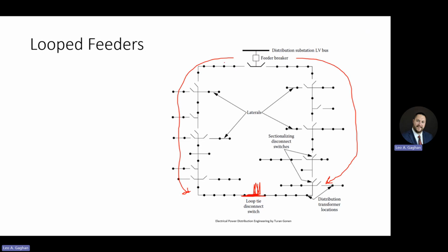Because let's say you had a fault right here. It's going to be easy for current to flow to get there, but much harder for it to come back around. Single feeder, or single breaker, wouldn't be an issue because we would trip off. But if we had two of these, let's just pretend that middle part didn't exist. It'd be more difficult for current to flow all the way around to detect that. We'd have to rely on a sequential trip.